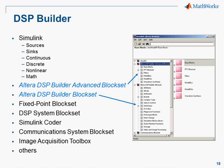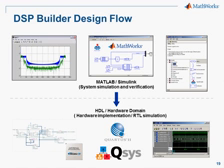Simulink consists of a number of libraries of building blocks from which designs can be built and tested. DSP Builder is shipped with 2 library add-ons to the MATLAB Simulink tools, encapsulating 2 preferences for design methodology: a WYSIWYG style, giving explicit control over pipelining and reset and enable signals in the standard block set, and an abstracted, higher-level style in the advanced block set, which allows the tool freedom for automatic optimization and pipelining. Both block sets generate HDL, provide automatic verification that an RTL simulation of the HDL generated matches the Simulink simulation, and generate Quartus projects and QSYS integration files. The classic block set also provides tools for Simulink-driven hardware simulation and signal capture from the SignalTap2 logic analyzer.